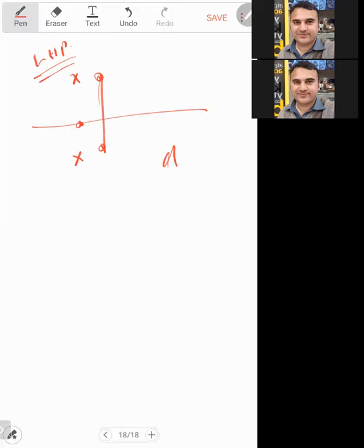So that is why this method of reversing is derived from the fact that the polynomial with the reciprocal roots of the original polynomial has its roots remain in the same left half plane, right half plane, or on the imaginary axis.